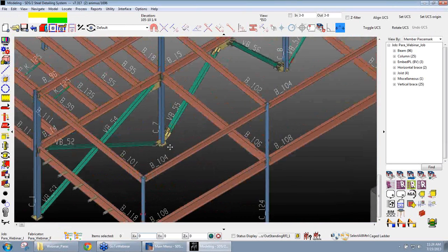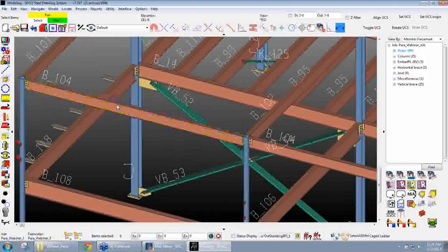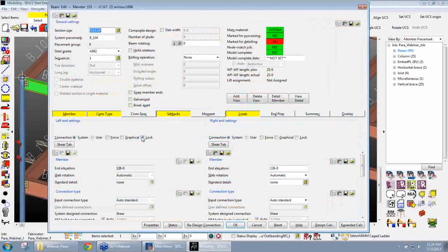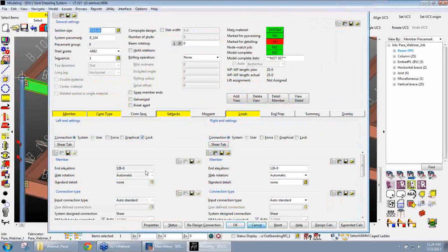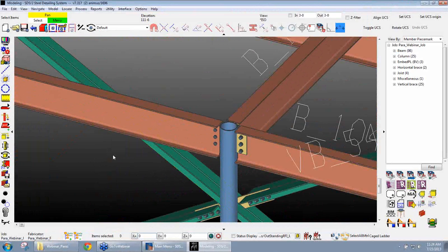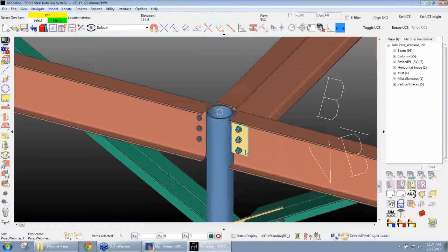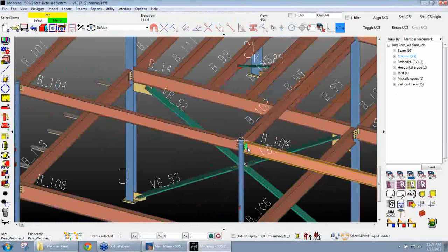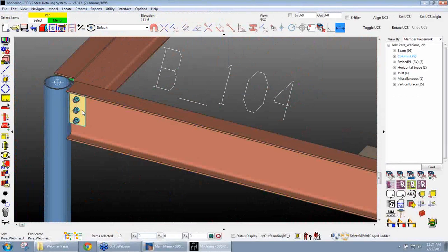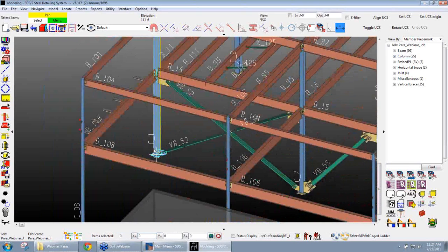And then if you noticed in there, I had one other scenario. Just as to show the example, I believe this beam right here, I do have set the left end to be locked, but it's not model complete. The right end is not locked. So I'm looking at these different particular shear plates on it, the F13s, and run that. Select my piece of material. You can see it's selected all my different materials. I have 10 of these selected, but did not select this particular F13 because it's on a locked end of a member.